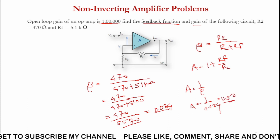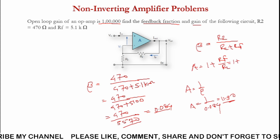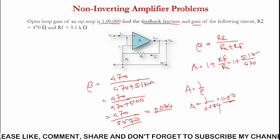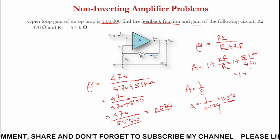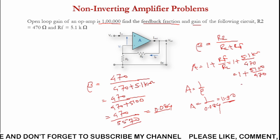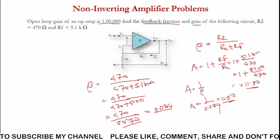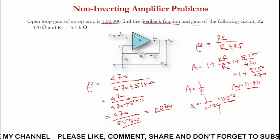Okay, so this is the way we can calculate, or we can put the value of 1 plus Rf upon R2. Rf is 5.1 kilo ohm and R2 is 470. So if we put the value, 1 plus 5100 divided by 470, you will get approximately 11.90. So you can calculate A and beta this way. This is the way to calculate gain and feedback fraction.